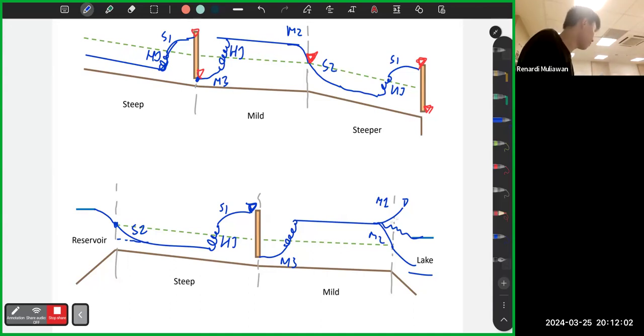What's high enough and low enough? High, I think, is just if it's higher, it's automatically M1. Low enough means the lake is lower than the YC, because for M2 to develop, it must pass YC. Understand? So if the lake is below YC, then there's M2. But if it's somewhere in between, between YC and here, then usually it's just a local transition.